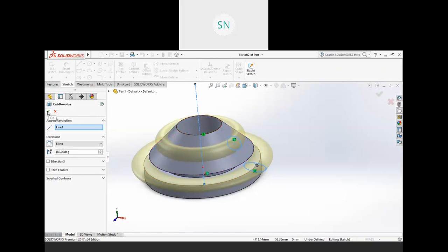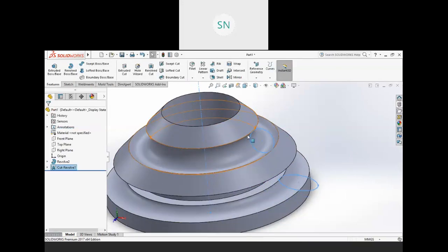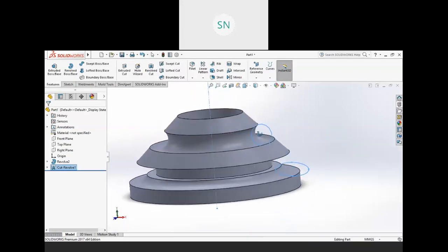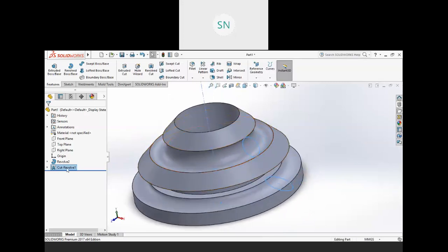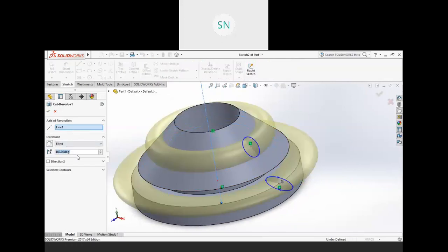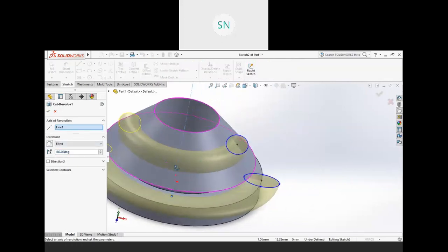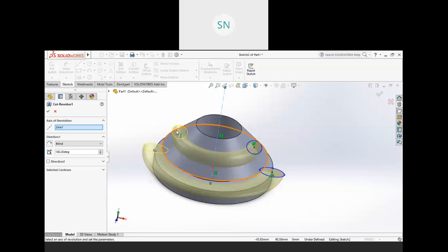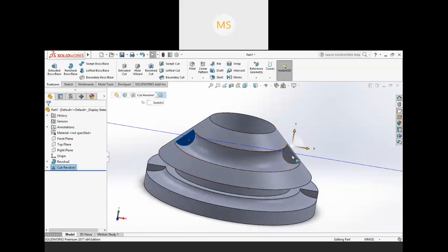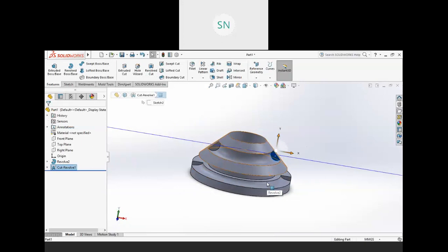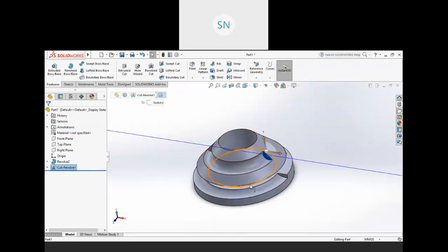But as you finish this thing, because we have a revolve cut operation, it will create a groove over there, that type of groove. Whatever solid is going to touch that revolution will be removed. Let me show you again. Edit. This time I am using 180 degrees, so you will get exact idea. See, we have this much revolution, and as I finish, you will get the result. So this much volume is going to be removed due to this revolving cut operation. So it is clear now. Revolve and revolve cut.